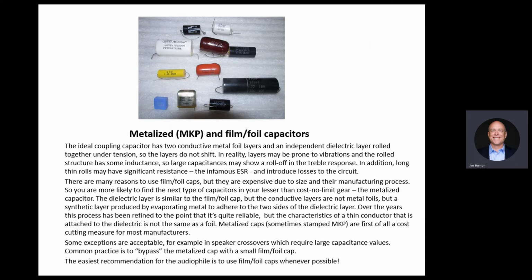It was like a few ohms over 1 inch. Then I took this one, I broke that, and you could go a few feet and you don't get 1 ohm. So there's a difference in quality. And this difference is very easy to spot because the more quality you put in, the bigger the capacitor becomes. Either the thickness of the metallized foils, or if it's a foil versus just depositing some aluminum vapor, it's a lot thicker.